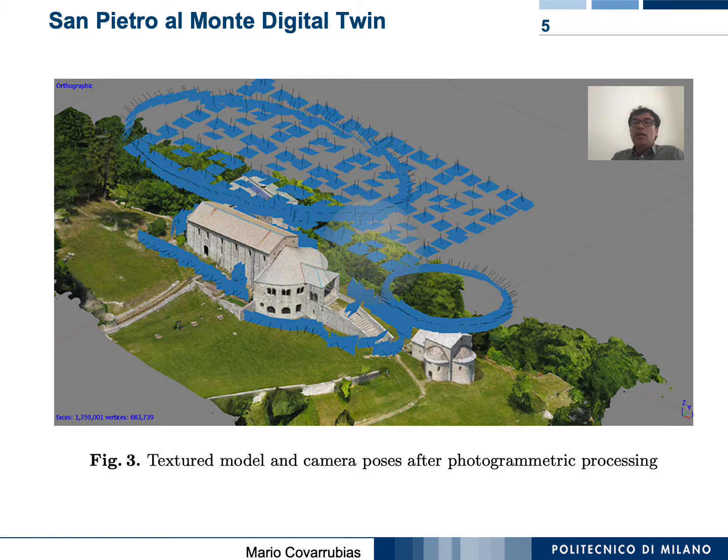And finally, additional terrestrial images were acquired using a handheld camera, Nikon D610, around the buildings. The set of convergent drone images has a tilting angle of about 45 degrees, allowing the connection of the vertical normal drone images together with the terrestrial capture.